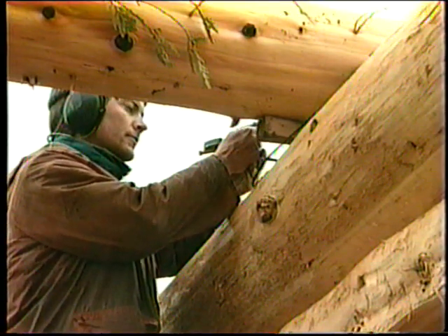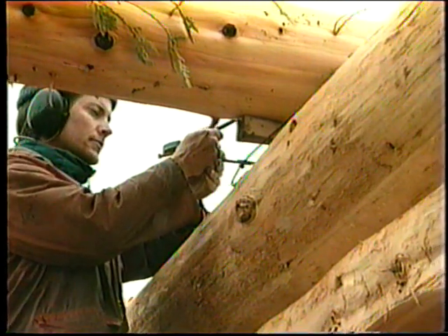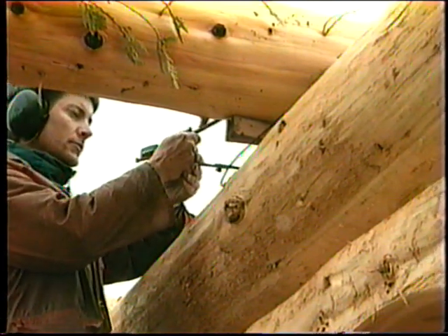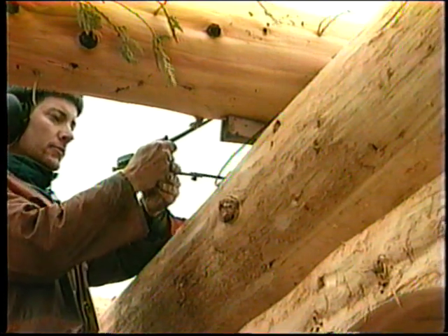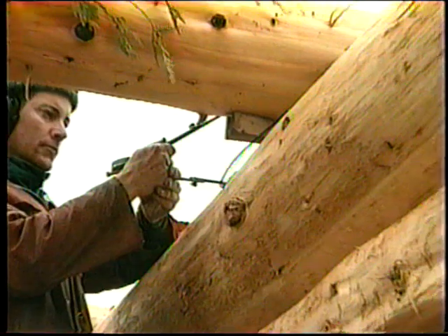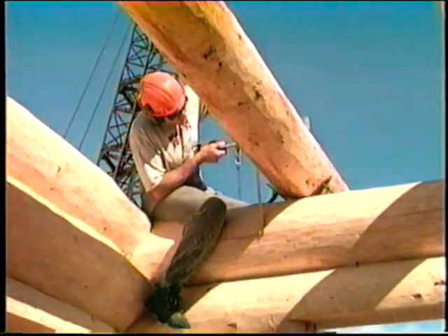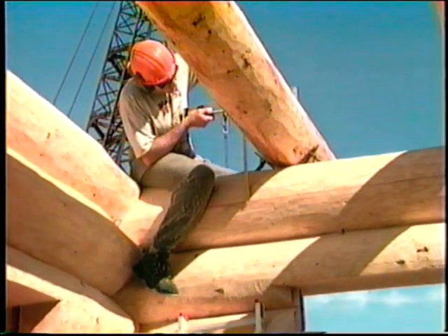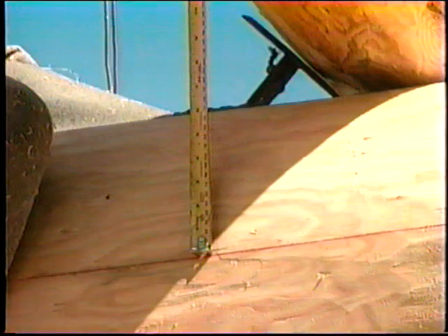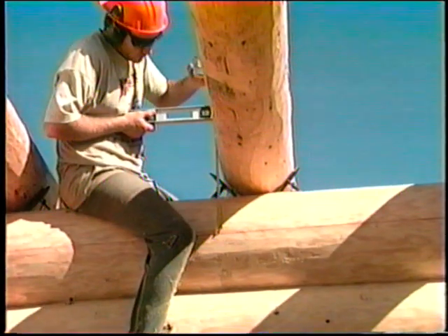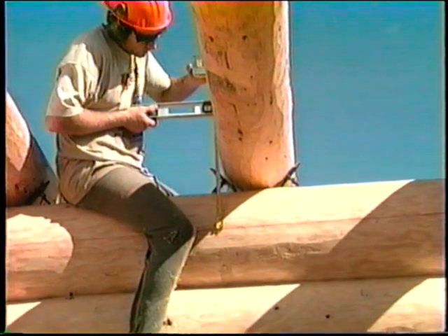Now you are going to scribe the joist down so that the tops of each will be the same height above your reference line. To do this, place a level across the large end of what you judge to be the smaller joist. Measure from the bottom of the level to the reference line. Let's say this turns out to be 650 millimeters.